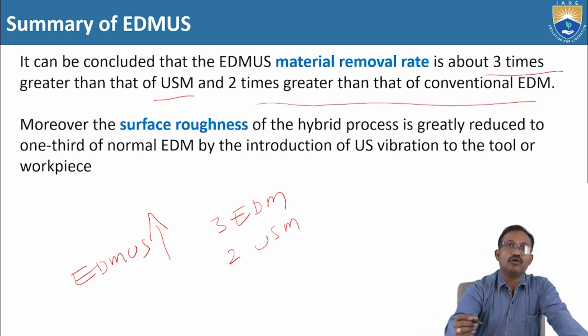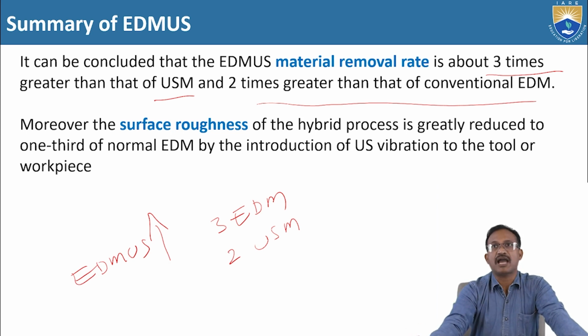Moreover, the surface roughness of the hybrid process is greatly reduced to one-third of normal EDM by the introduction of US vibration to the tool or workpiece.